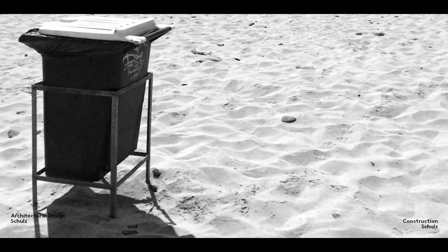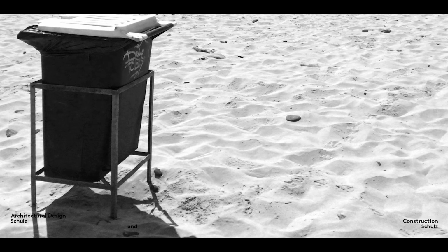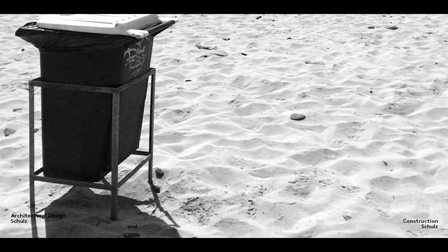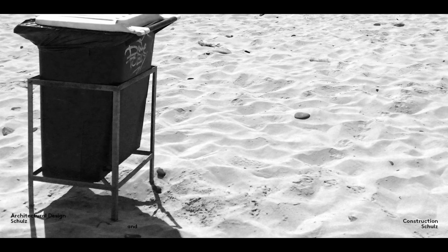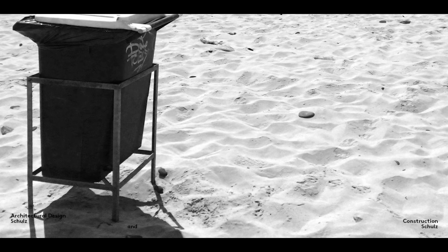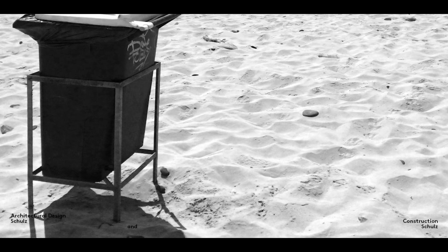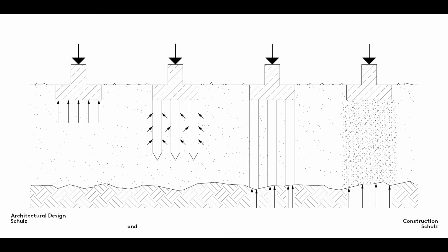This litter bin on the beach is leaning at an angle because its weight is concentrated on 4 thin legs in the sand, which makes a poor foundation. The stability at the 4 points of contact varies, so the litter bin is in danger of falling over. Sinking the 4 legs deeper into the ground, placing a slab between the legs and the sand to distribute the load evenly, or reinforcing the sand would all help. More or less the same methods are available for stabilizing a building.